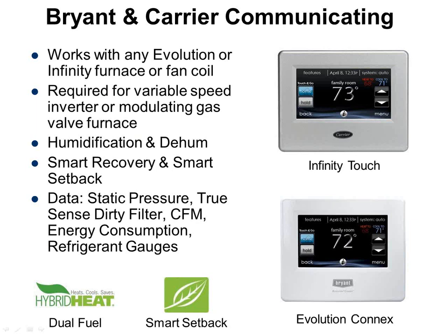And you're thinking, what the heck? I told it not to turn on until 65. It's calculating if it's smarter for it to run at low fire for a little bit of time throughout the day versus wait until it's almost time for you to come home and then go to high fire. So it's calculating that to save you the most energy, because at this point we're fighting for a few therms here and there or a few dollars here and there worth of energy. So it'll calculate that stuff and try to optimize it.